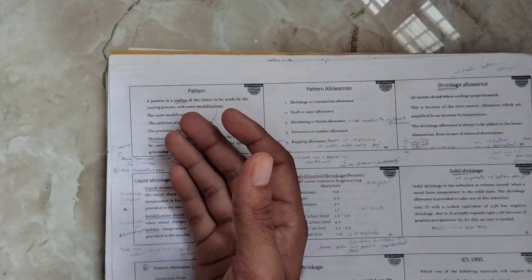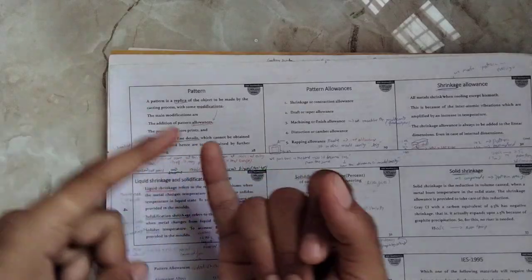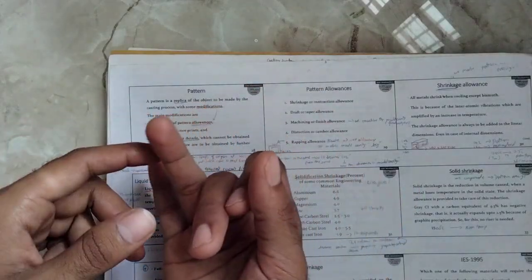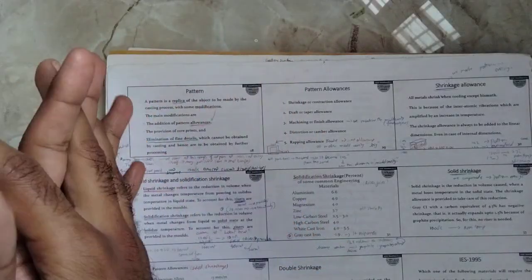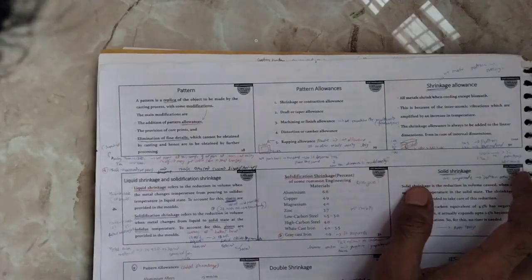I also told you about the pattern, which has a few allowances: shrinkage or contraction allowance, draft or taper allowance, machining allowance, distortion or camber allowance, and warping allowance. So in the pattern allowance...